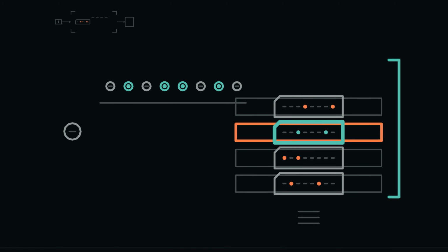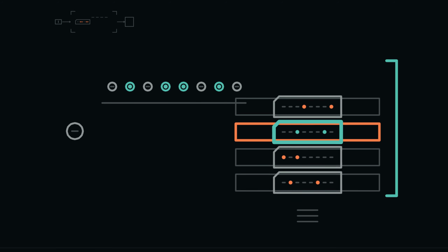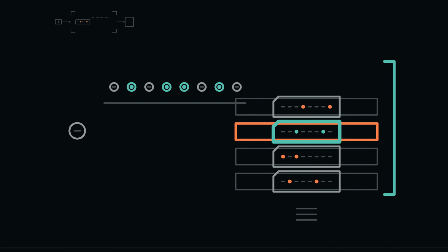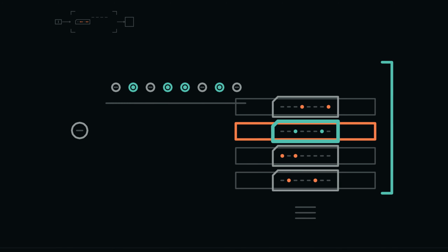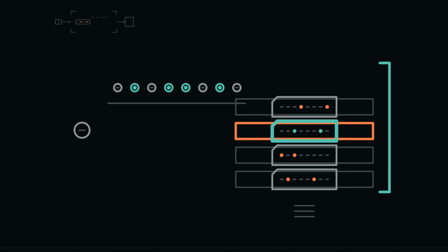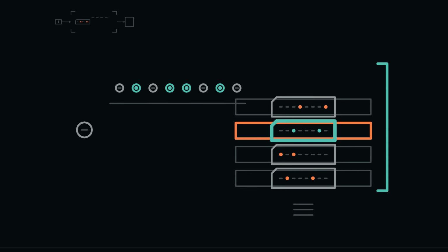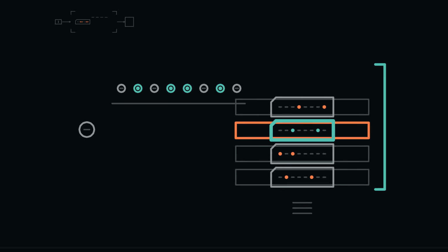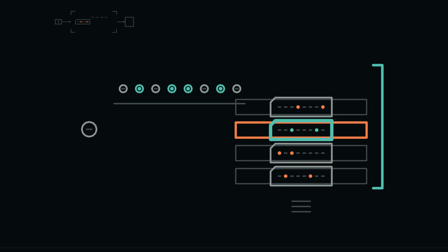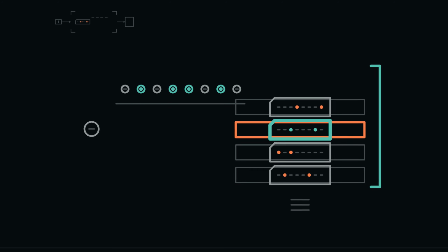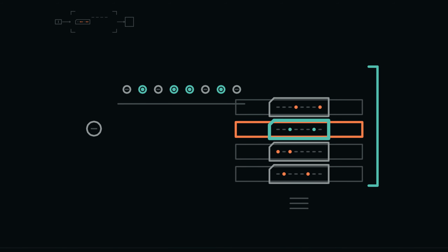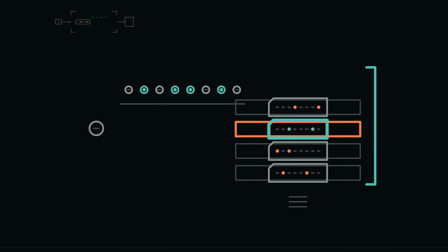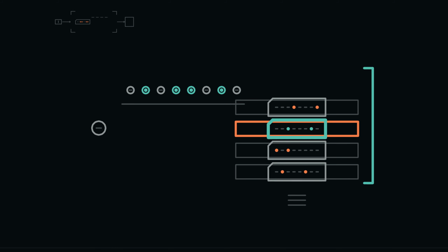Predict a large array case. The address is hexadecimal A6. The decoder must activate output A6 and no other. If write is inactive, every row retains its state regardless of the data input. If read is active, the output selection path represents the byte already stored at A6. If write becomes active and the edge arrives, only row A6 captures the presented data byte.